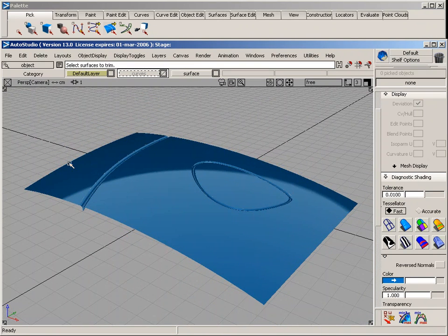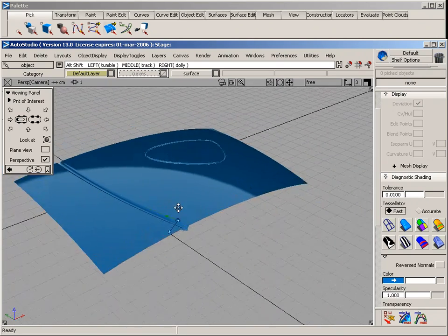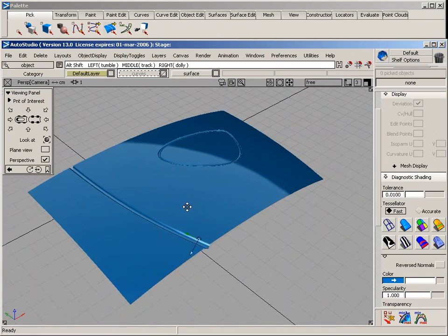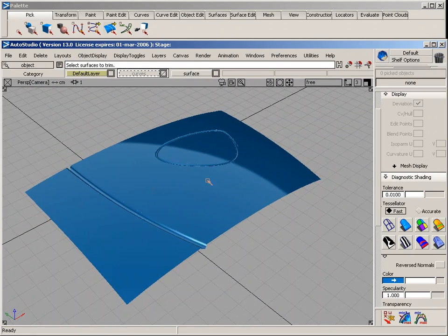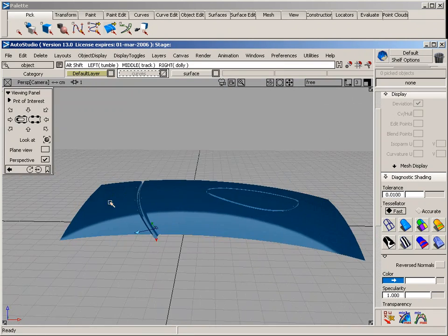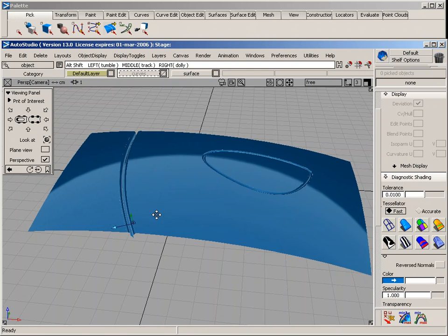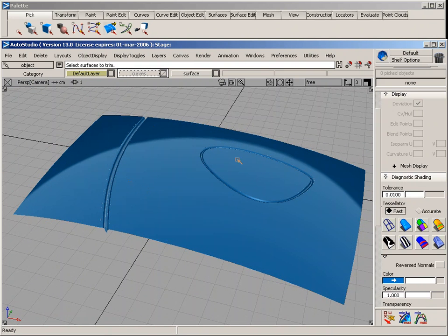Now that we've covered a whole bunch of these new surfacing tools, such as the rail tool, and seeing some of the different options you can do with this, you also got introduced to the first idea of temporary surfaces. In addition to that, see how you can do some quick indication of part lines and other details. I'm going to start to use all these to create a simple demonstration on how to create a mobile phone.